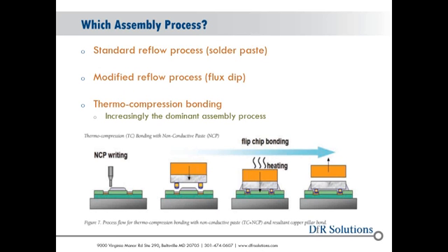Also possibly a little more of a risk in terms of the underfill to the BGA, as well as risk in terms of moisture sensitivity level, right? Increased MSL risk there if I don't have good adhesion. What we're increasingly seeing in terms of the dominant assembly process is thermocompression bonding. So I'm actually not doing a classic reflow. I'm actually heating the device and applying pressure. What's amazing about that is, and I'm using non-conductive paste to do it, I'm just using a cap on top of the solder pillar as my assembly material.